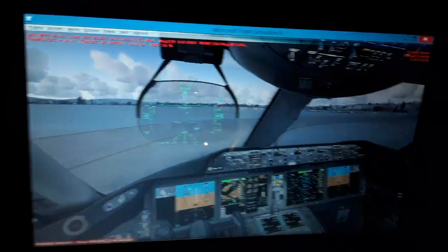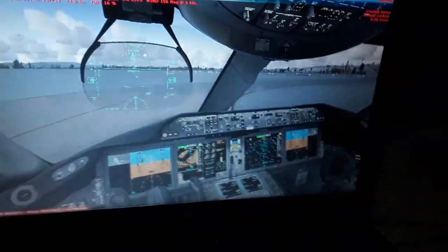I'm going to start with the primary flight display. You can also see in the navigation display other aircraft that fly around our own aircraft using the transponder, which is a transmitter receiver that transmits radio frequency to other aircraft and air traffic control and receives from other aircraft. You can display the other aircraft's position.